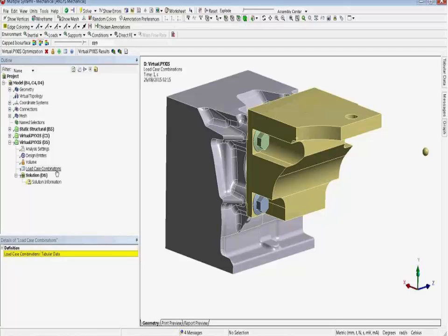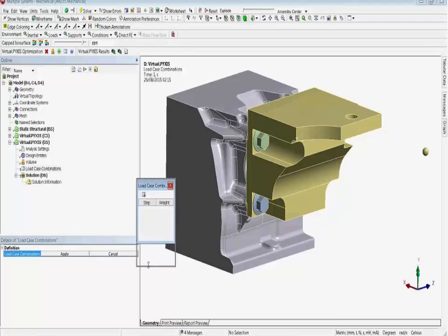But as you have separate load cases, you have to give the software the opportunity to maximize the stiffness considering these 3 situations. So the software tries to get the best design from these 3 situations. So here I call the 3 steps, as I showed you before, 2, 4, and 6. I do not consider time step 1, which is the screw pretension, because the energy of the screw pretension will be present when you consider each of these steps.